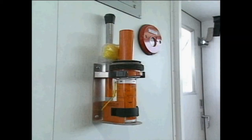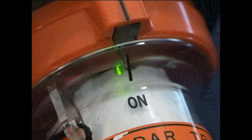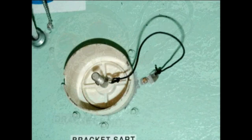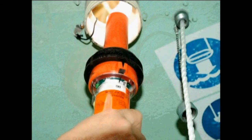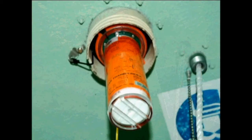When used in a life raft or lifeboat, it must be removed from its location on the ship and switched on after being brought on board the raft or boat. In a lifeboat, there's an area where the SART can be installed on the ceiling. Remove the SART mounting unit's bottom plate, pull the string to remove the SART from the hook, then push the upper part of the SART out of the boat.